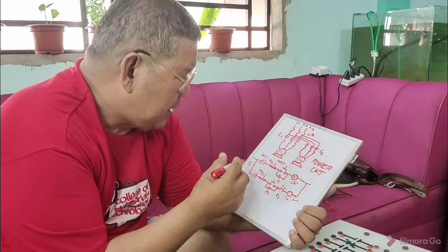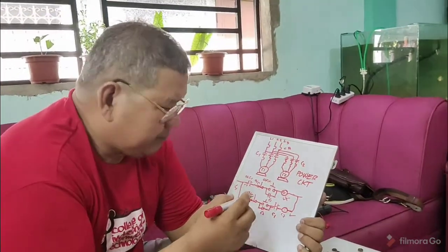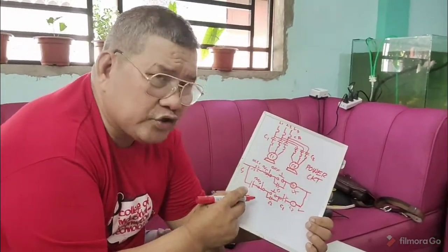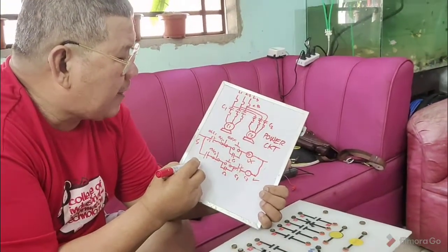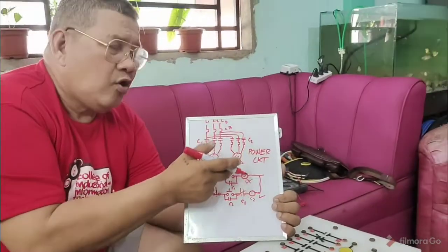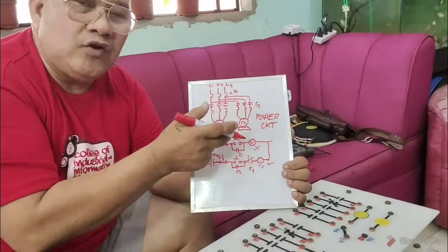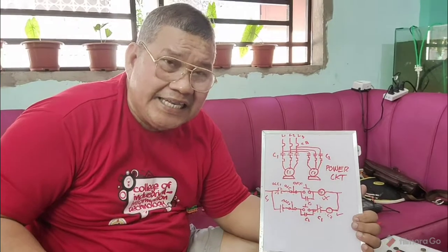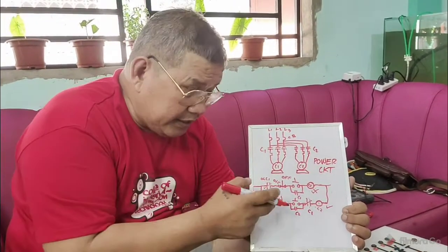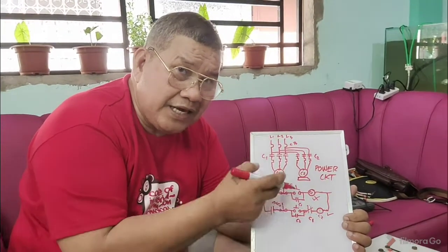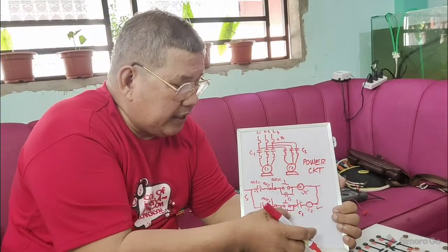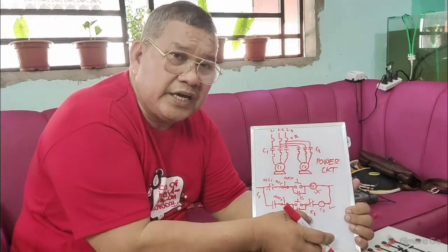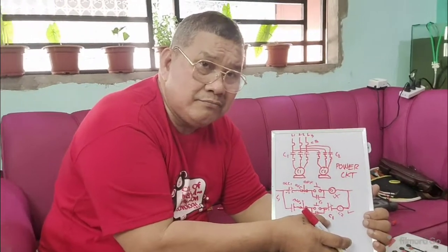That is it. But I'm going to add another condition. In this condition, listen: if any of the motors is overloaded, the two will be off. Any. Remember, in this problem, not any. Because if conveyor number 2 is overloaded, conveyor number 1 is still running. Right?